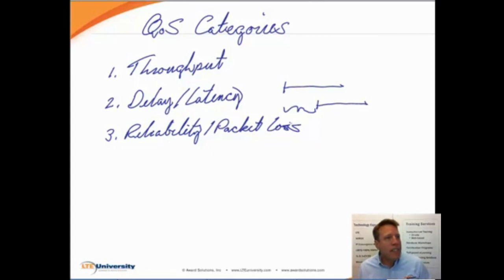Well, it turns out that some services, like for instance voice, it's okay if we don't get all of the voice data. For instance, if we're breaking the voice into 20 millisecond voice frames and sending it out, typically cellular networks are engineered so that they drop 1 or 2 out of 100 of these frames. And we're creative with what we do when frames get dropped, and really most of the time we don't even notice it.